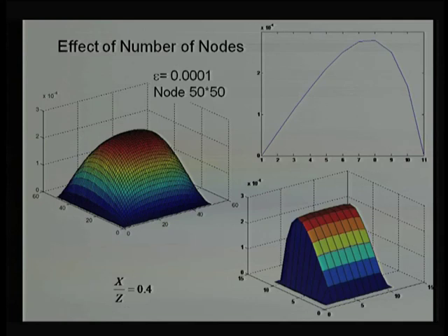If that is going to change the viscosity, then we should account for that also, and some extra effort and extra calculation will be required. In addition, we know viscosity is a strong function of temperature. An increase in temperature will happen if there is an increase in pressure and more friction at the surface. That is going to change the temperature, and the temperature is going to change the viscosity, and viscosity is going to change the pressure profile. So, they are dependent on each other.